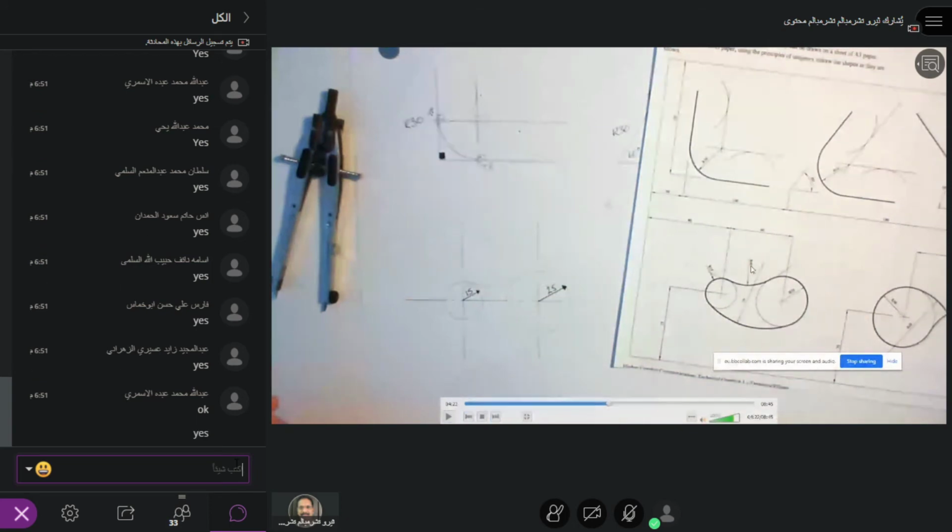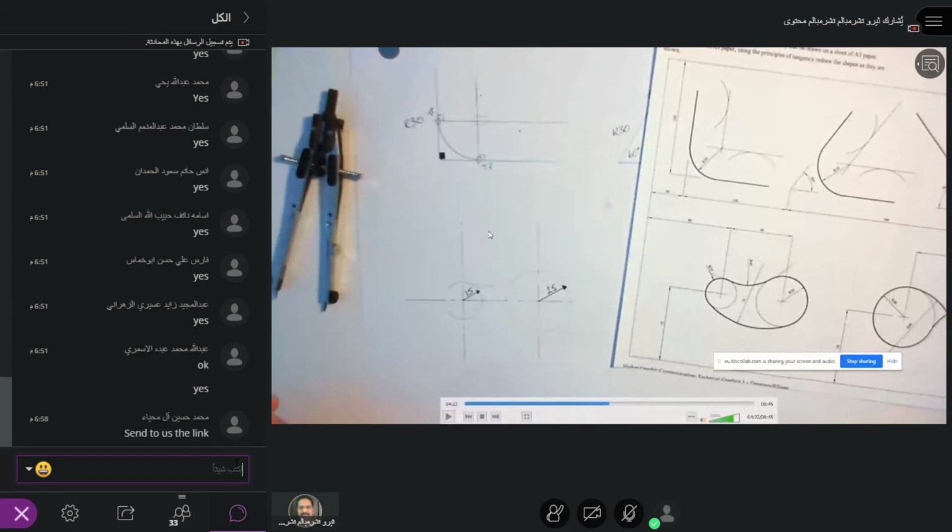So, what he was saying, this is 15, but the radius is 40 from there. So from the center it should be 40 plus 15 somewhere. So he first makes the arc, and he doesn't know where exactly it is, because the point should be a common point that will make 40, that will join these two circles.